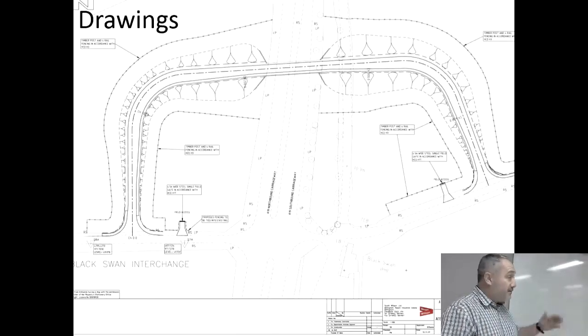Bridges can carry rail, people, horses, boats. This one was designed for cars and people and horses. Because of the horse use, that impacted upon the gradient. So you'll find that as soon as you start looking at the highway design manual, you have to have a 5% gradient, otherwise the horses can't make it up, apparently.